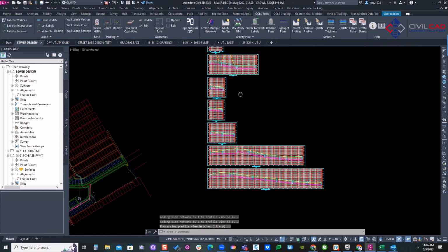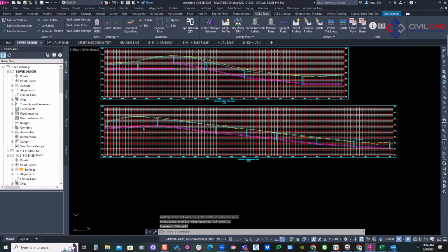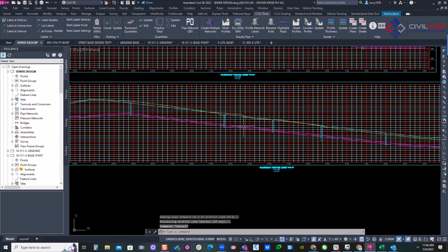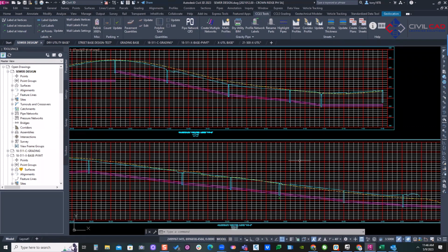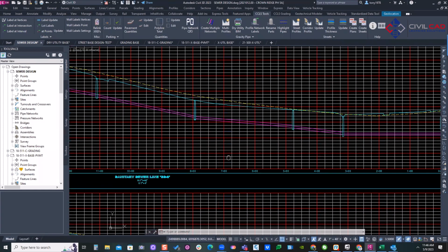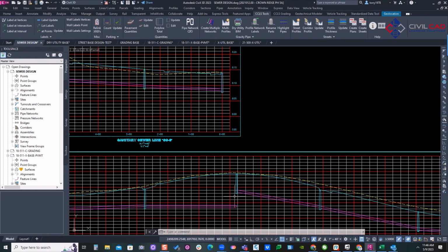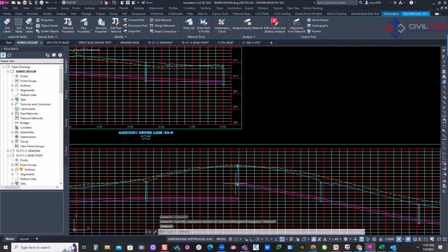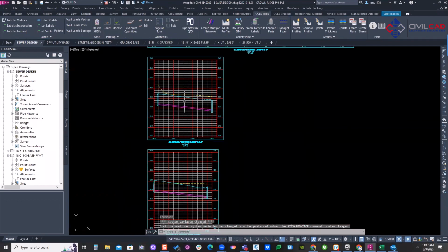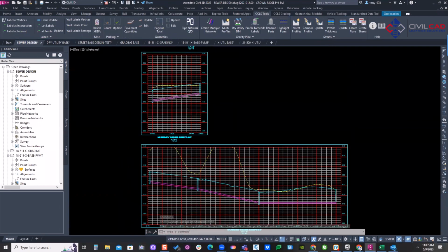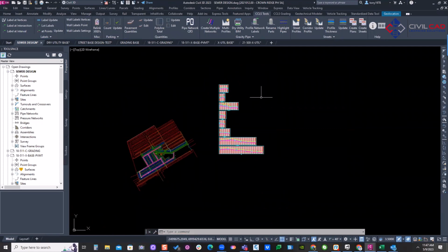There we go. All right, so you see here, I don't know if y'all can see, here's my sewer, and it's trying to maintain that 5 foot of cover. Okay, it's not designing, it's just trying to maintain a 5 foot of cover. So it created all the profiles, as you can see here. Now here's one little bug here, I'll just notice on this one manhole, but the rest of them are all created, as you can see. Every profile has been created for every pipe network, okay?